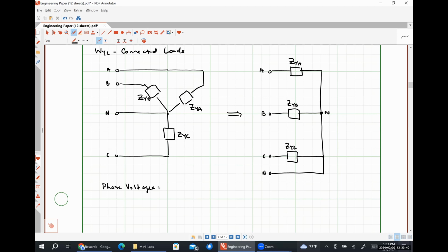So how about you hit me with a second subscript for each of those voltages? N would be the second subscript. Absolutely correct, Isaiah. So we would have a voltage V capital AN, V capital BN, and V capital CN, representing this voltage drop, VAN, this voltage drop, VBN, and this voltage drop, VCN.